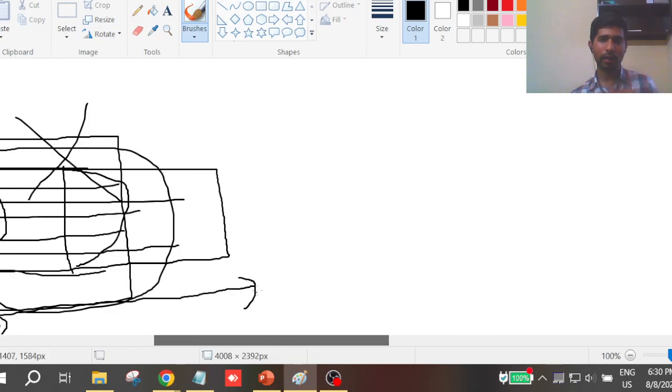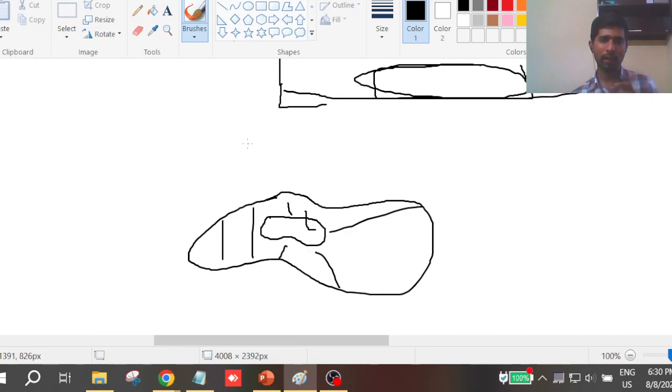The elements become very small, and a curvilinear mesh might lead to convergence issues. So usually you go with an unstructured mesh here. Till now we discussed the different types of mesh and when to use a structured or an unstructured one.